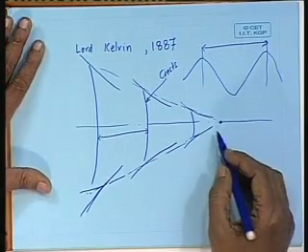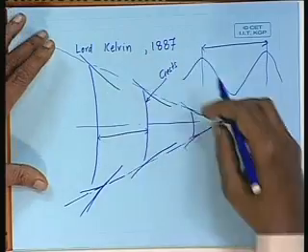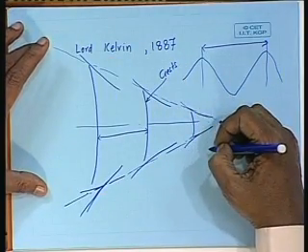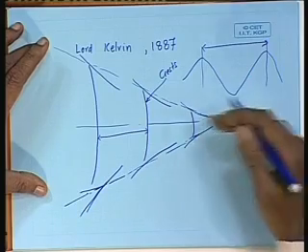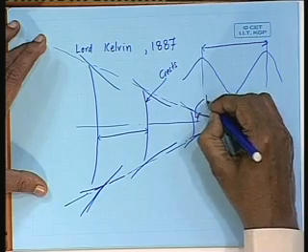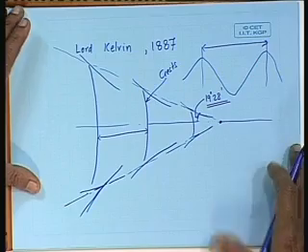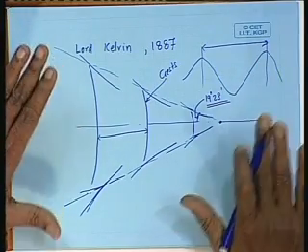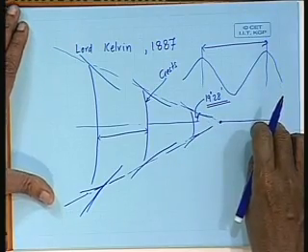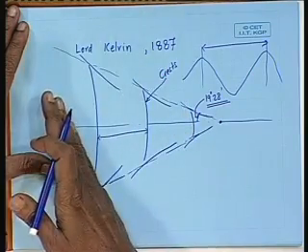But surprisingly, he also showed the entire wave system is contained within two straight lines emanating from the pressure point, making a constant angle on either side with the axis of movement, and this angle is said to be 19 degrees 28 minutes. Okay. He showed that this is how it would happen. So, when a pressure point moves on the surface, two sets of waves are generated, one set is divergent waves and one set is transverse waves.